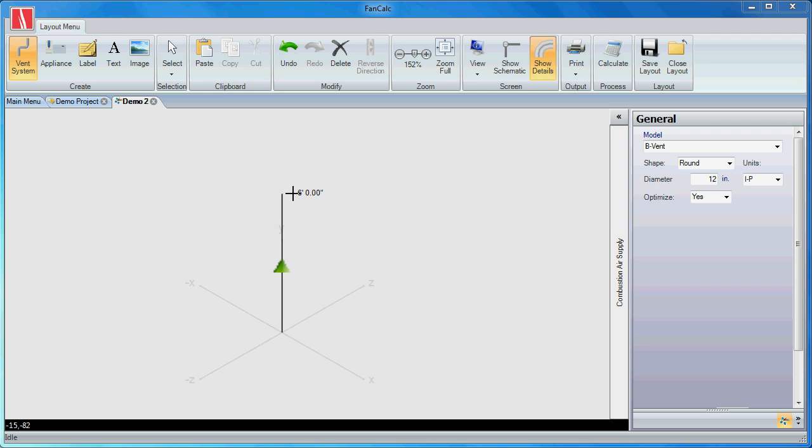So if you picture a plan view, basically what you want to do is take that plan view and pretty much rotate it 45 degrees clockwise. So anything that you would normally have going sideways is now going in this direction, and anything going deep or towards yourself would now be going out the z-axis. That's really the easiest way to do it.